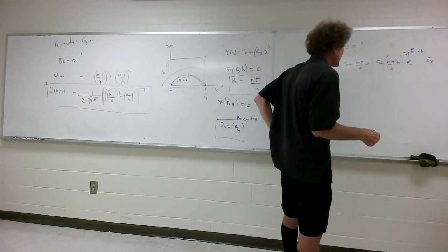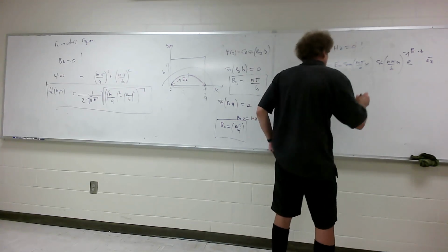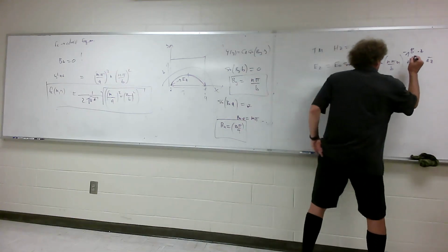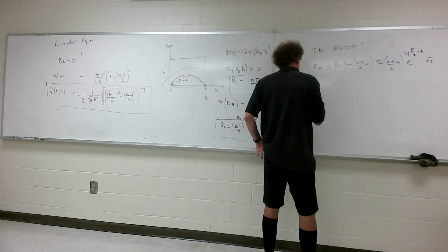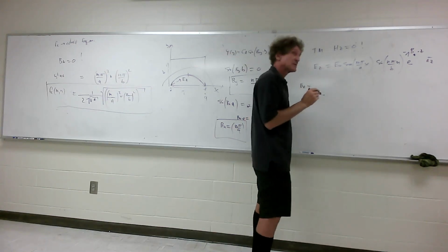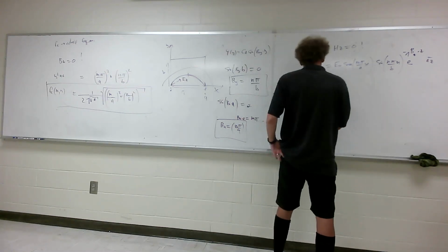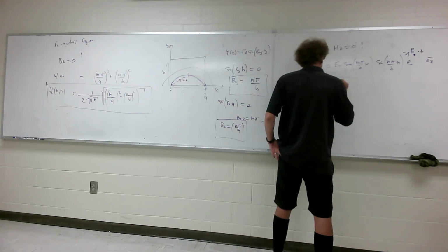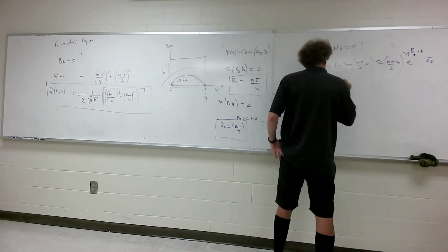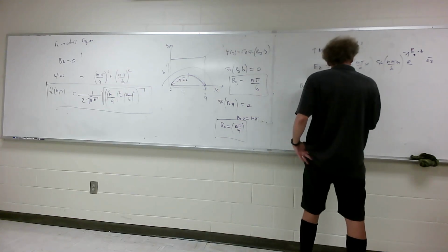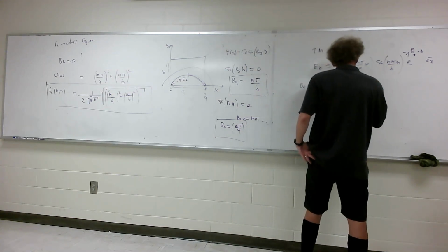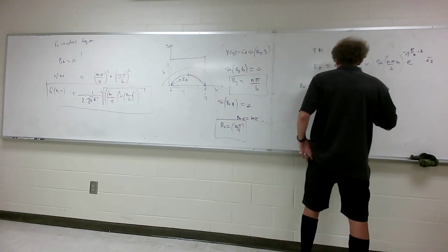I take a look at this. I know that that beta there, maybe I better call it beta z just to be consistent. That beta z is equal to, please write this down, the square root of omega squared mu epsilon minus, I'm about to simplify life, (m pi over a) squared minus (n pi over b) squared.